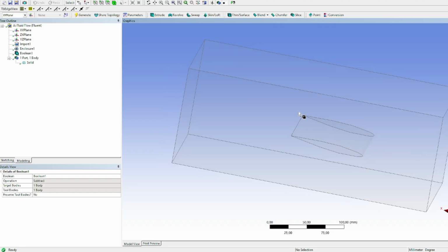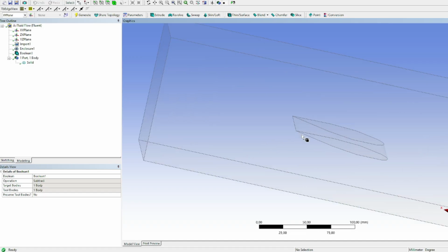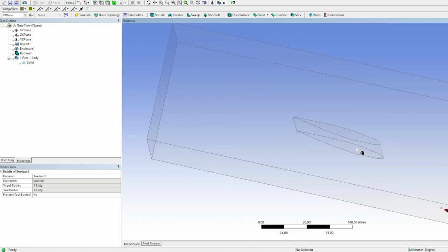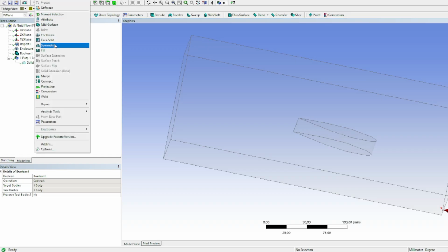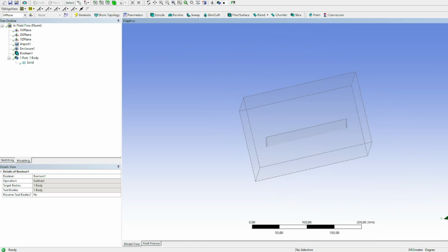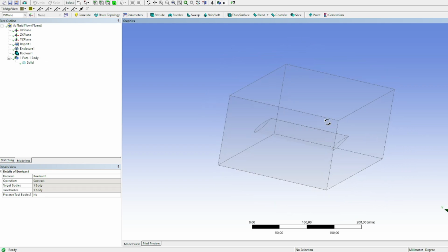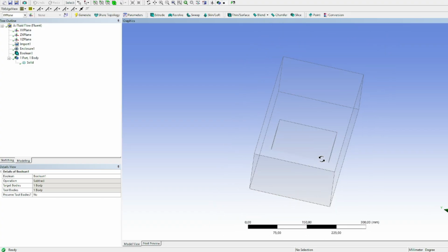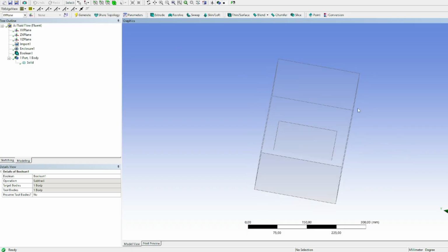If you had any type of problem, try with another mesh, and if not, try different adjustments like I do with the rear wing here, that maybe has an angle that is too little, or there are surfaces on your body. Before doing anything, if your model is symmetric, like in my case, that is a wing, you can cut the model in two, and it will be the same because it's symmetric, and you can just analyze one part because it's not necessary to analyze both.